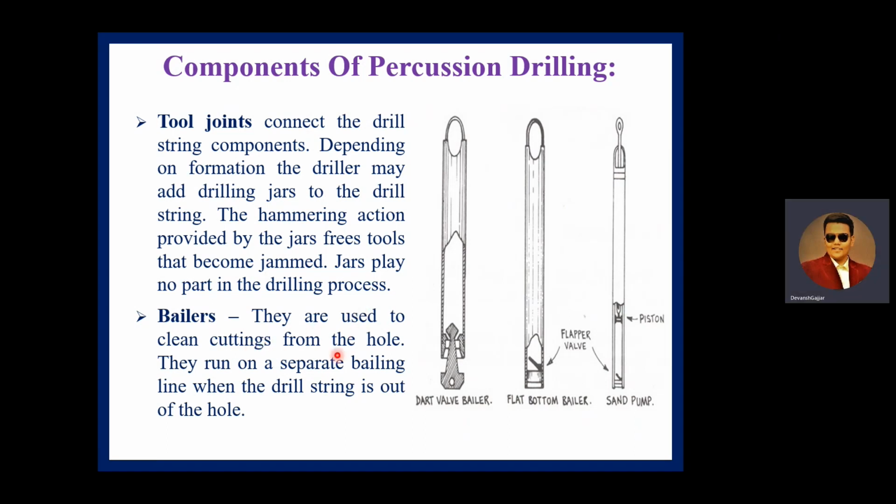Balers are used to clean the cuttings from the hole. As we have seen, as the baler gets filled, the tool is lifted to the surface and the slurry is removed. So they are run on a separate baling line while the drill string is out of the hole.